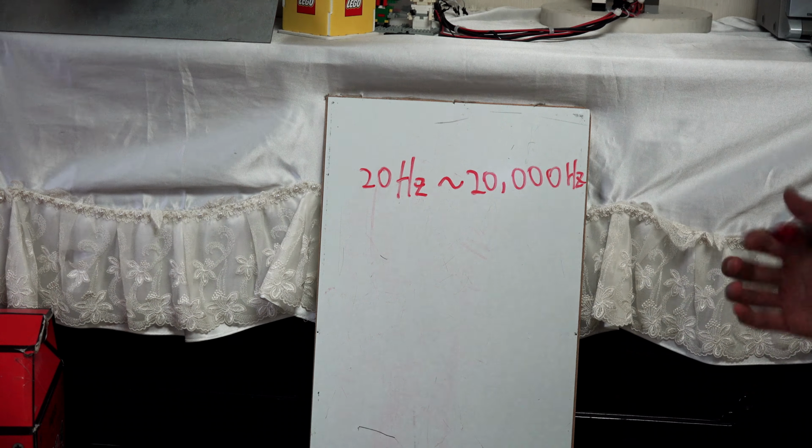I found a datasheet for this ultrasonic sensor on Google. This one, the trigger input, is just an input, as you can see. So we can trigger this with digital write on Arduino, for 10 microseconds, and that's all.